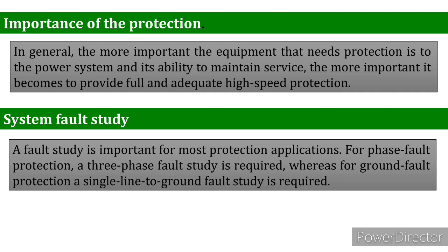The second one is the system fault study. A fault study is important for most protection applications. For phase fault protection, a three phase fault study is required. So online information concerning a fault on the line side at an open breaker is frequently important. The fault study or the fault analysis, you can say, may be done by using different softwares, and online softwares can also be used.